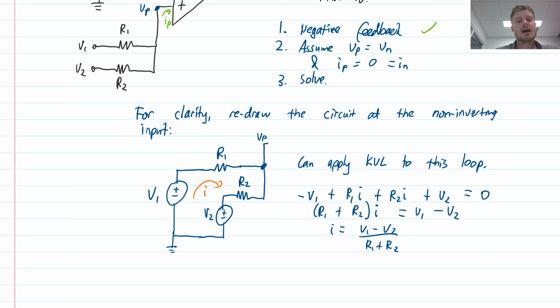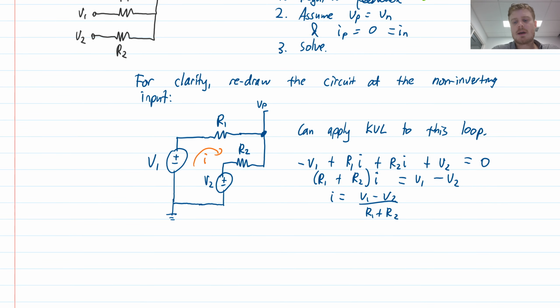All right, but I actually want to know what is the voltage. So one way to calculate what that voltage would be is to start from the reference node and then just follow any path through the circuit until I get to the point that I'm interested in, and I just accumulate all the voltages along the way. So I'll do this in the direction of positive current, so that I make sure I don't have to do anything tricky with the signs.